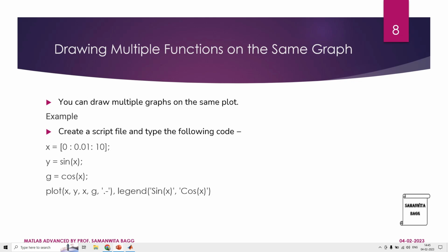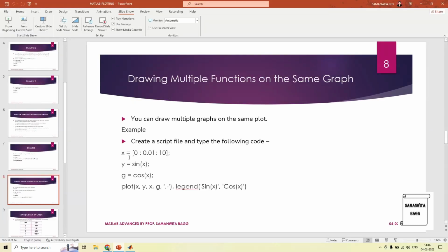Now we'll go for drawing multiple functions on the same graph. You can draw multiple graphs on the same plot. This is an example for it. The value of x is given. We have written y is sine x, g is cos x. And we are going to plot x,y. Also we will be plotting x,g. Now for x,g you can see here a different denotation has been shown and the legend over here is sine x, cos x. We'll take this to MATLAB and see